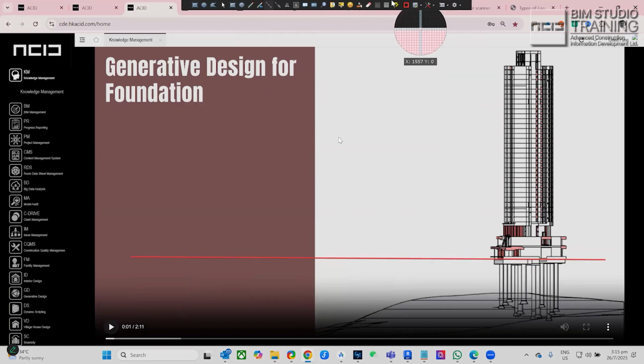If this is ground, so I have a design, the piece of the building, on this position. Now it has a foundation. The foundation lands on the rock, but the rock is not flat. So if I put it in this position, all these different piles will have different lengths. But if the building design moves to another position, then it will have a different depth, different condition.